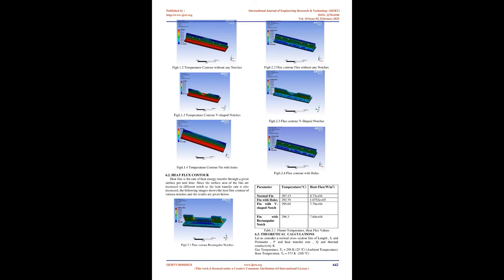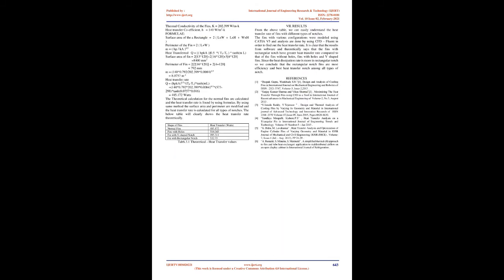Results. A three-dimensional model is developed to investigate flow and heat transfer rate in the automobile fins. A series of numerical calculations have been conducted by Fluent and the results are presented to show the effects on temperature distribution, overall heat transfer coefficient, heat transfer rate, and temperature contour. Due to the change in shapes of the fins, the temperature distribution varies in the above figures and it can be determined by using CFD Fluent.